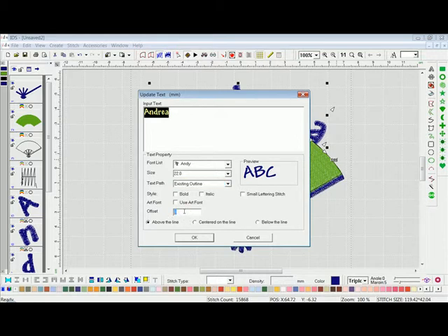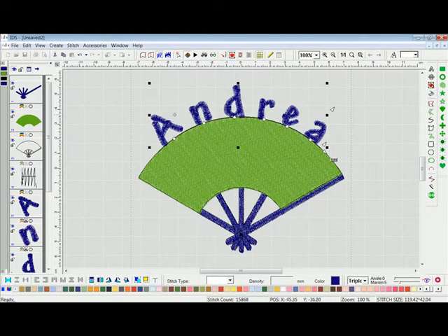This time I'm going to take that offset. We're working in millimeters. I'm going to left click, hold, and highlight so that our measurement is highlighted. I will change that to 2 millimeters, so it'll sit above our baseline 2 millimeters. Press OK, and now I can set the beginning and end points.